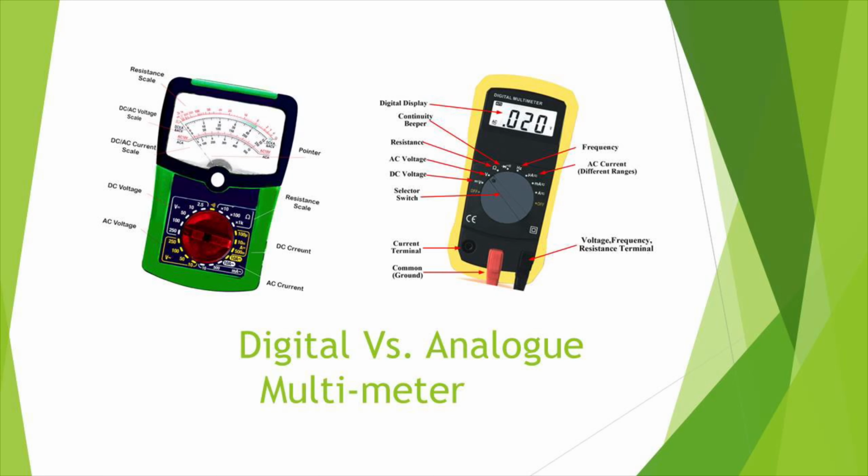For varying signals, if you have a voltage or current or resistance that continually changes, then a DMM will vary its reading on the display. Although the ADC on the digital multimeter is capable of very fast readings, your eye will not read the display at this speed, so the readings are slowed to a few readings per second.